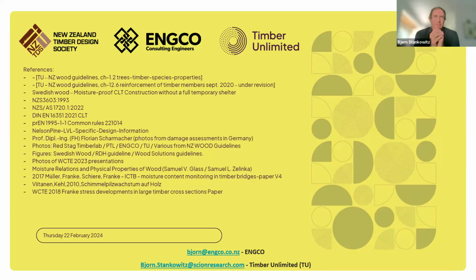that will mislead you into a way that you probably don't want to see. One thing to say for the moisture management, it can fluctuate quite a lot, up and down, up to 2%. So therefore, pushing the levels to your limit and then measuring, you have to be mindful that the measured moisture content might actually sit slightly higher. And if you're already on the boundary of something that would cause you grief, you should ask yourself twice if you're still happy with it, or if you're not, do something.